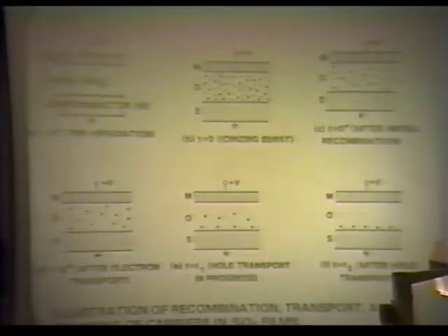And it's going to basically shift the threshold voltage, you know, the voltage that's required to turn this device on and off. It's going to shift that value required. And pretty soon, in the case of an N channel, you've accumulated enough charge along there that you've turned it on, you can't turn it off. And pretty soon in the P channel, you've accumulated a sufficient amount of charge in the oxide that you've turned it off and you can't turn it on with the normal biases. So your CMOS doesn't work anymore.